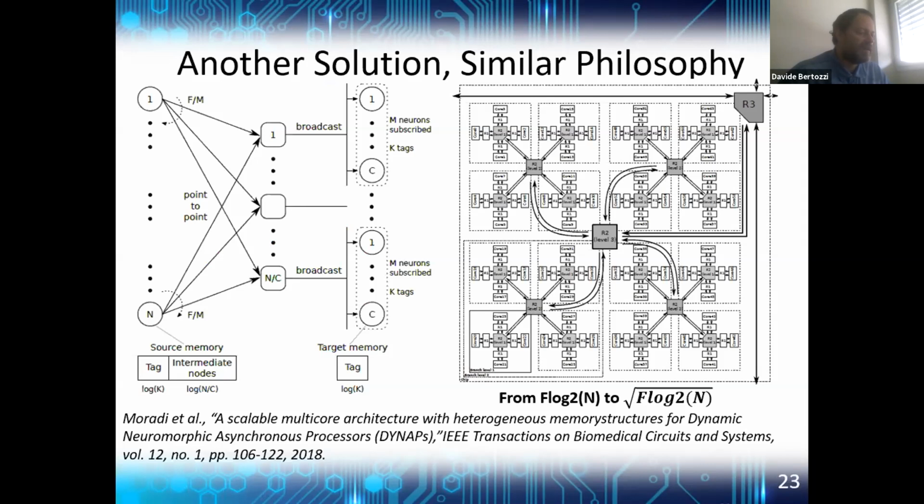It's just an alternative realization that, by defining specific connectivity requirements of neurons with all other neurons, by limiting these connection capabilities, and by properly arranging the network on chip in a hierarchical structure, they end up limiting the memory requirements to program the connectivity.